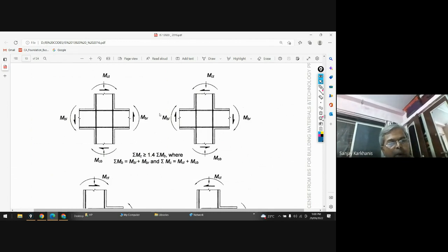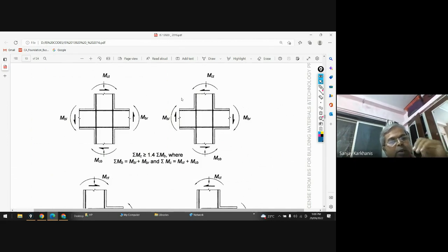Then again it is getting pulled and pushed. So because of that, there will be heavy shear stress. Failure might come over here, and that's why if this joint is not strengthened enough, then because of that pulling and pushing, that activity will create a crack between the concrete and the reinforcement periphery. That means failure, and that failure is very detrimental. Once the joint of the structure fails, your structure is going to collapse, and it will collapse in a brittle manner.